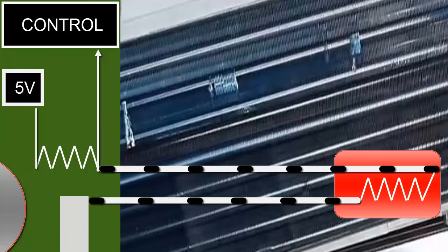12. There is a less frequent possibility that there is a problem in the sensor circuit part located on the electronic board, such as a trace or the internal resistance of the electronic module itself. In this case, the component must be replaced. To detect this, it is recommended to connect the sensor and measure if the voltage at the sensor's power pins shows a voltage, which should always be very close to 2.5 volts if the card is energized.